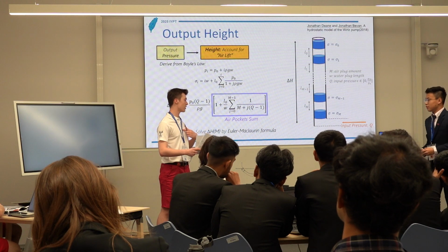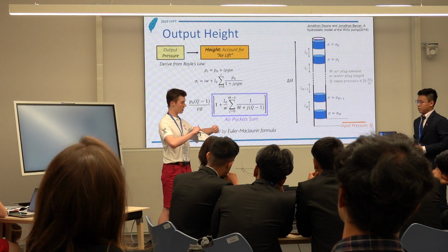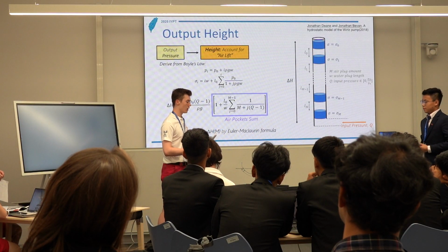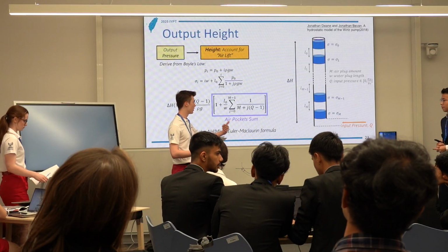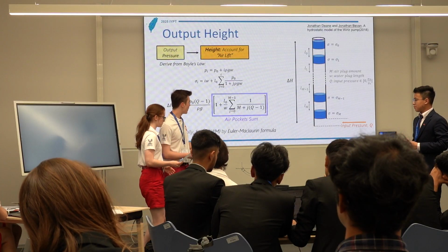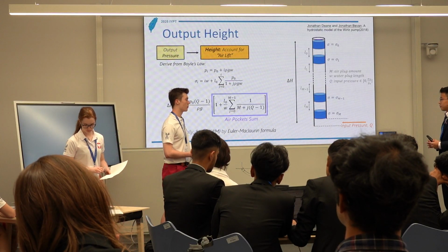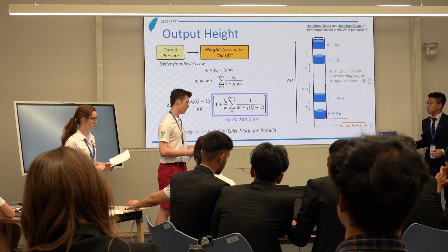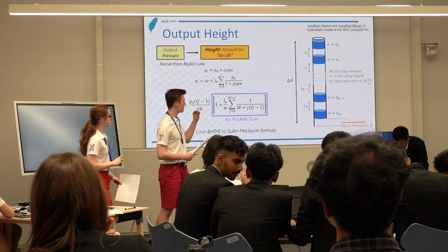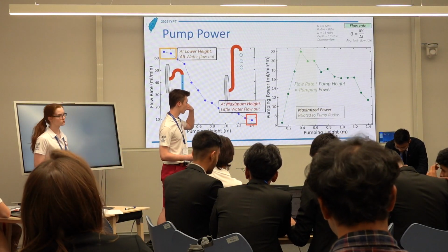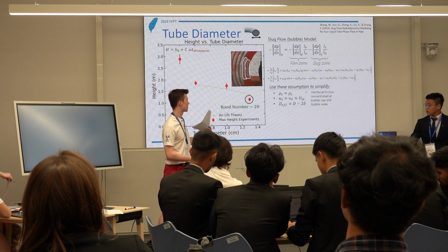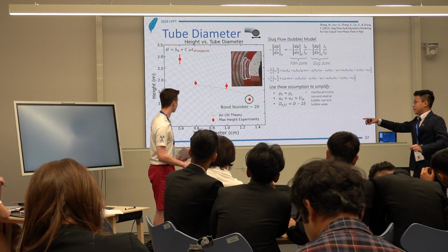Okay, I actually believe that you could have used a different rotary coupling that would allow you to have the pipe pumping directly in the vertical direction. This would improve the efficiency of your experimental setup. Now, please show us the slide with the Bond number. For what maximum width of the pipe were your experiments? Yes, as I said, 1.3 centimeters diameter.